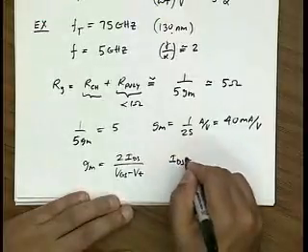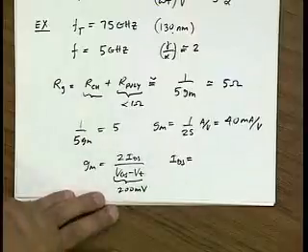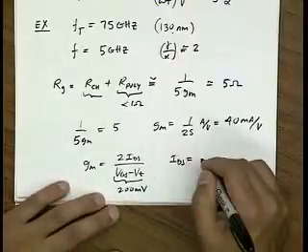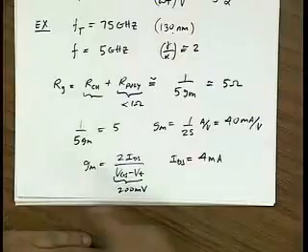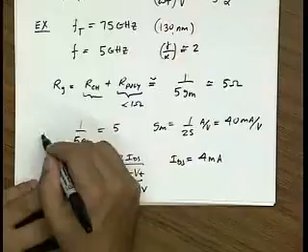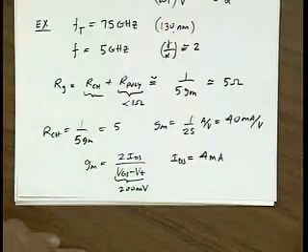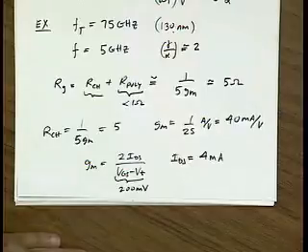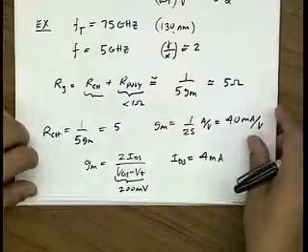Let me assume VGS minus VT, just to put a number in here, is 200 millivolts. That gives me an IDS of 4 milliamps. So already you can see that in order to get the channel resistance to be small, I have to bias the device with a substantial amount of current. But 4 milliamps is reasonable. It's not low power, but for many applications it could be acceptable.